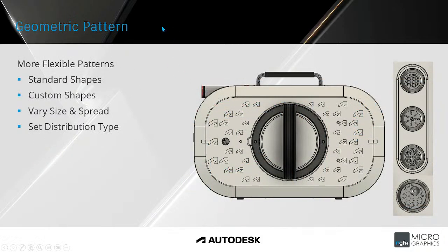Moving on to geometric pattern. This allows you to create more flexible patterns within Fusion 360. So we are not stuck to using just a standard rectangular or circular pattern. The nice thing with this is that you don't have to have any geometry to start with that you need to pattern. You can basically pick a face, and there are standard shapes that can be used on that face.